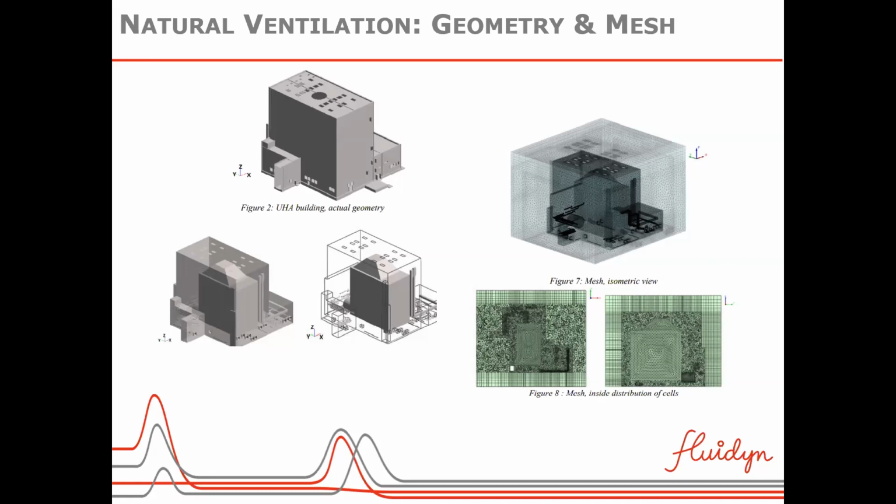From a ventilation point of view, I forgot to tell, we can specify the boundaries as isothermal, at some particular temperatures, or as a heat flux. That heat flux can be constant or variable, depending upon the user's inputs. In this case it's a constant heat flux emitting from different surfaces. It's a domain where the different equipment inside has its own heat generation. Our interest is, once it reaches the steady state, how the temperature distribution is inside, and whether it goes beyond some particular limit from a comfort point of view. That was the interest in this particular study.